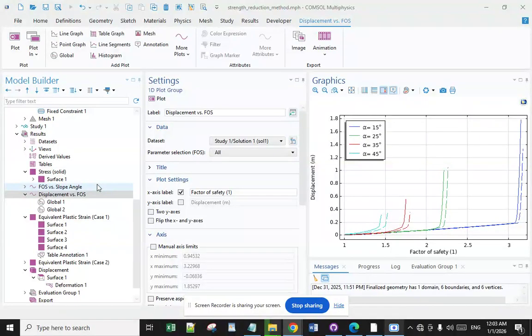There are two definitions for the factor of safety. The ratio of a structure's absolute strength, structural capability, to actual applied load. This is a measure of the reliability of a particular design. This is a calculated value and is sometimes referred to, for the sake of clarity, as a realized factor of safety.